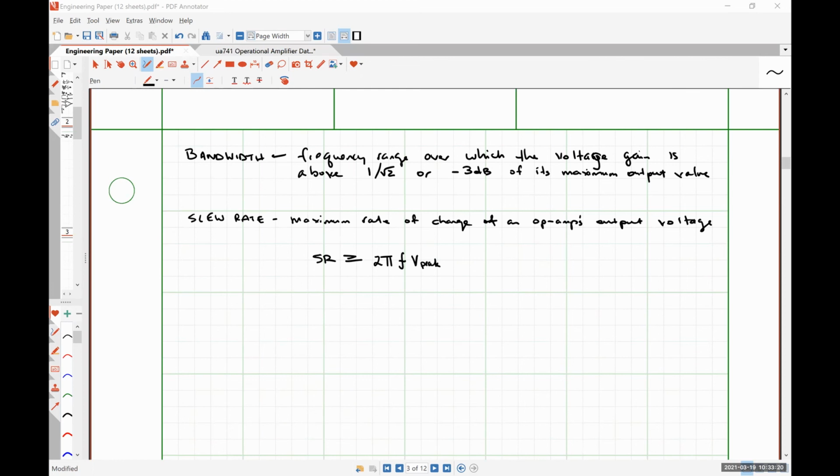And you can get that just from looking at it as from an impedance relationship, where it's a non-inverting amplifier where you have the voltage gain is 1 plus Z1 over Z2 for this guy. So that's not real difficult. How does the addition of the input bias current affect the linearity of the circuit? That's a good question. You guys figure that out. I'm not going to answer literally all 7 of them for you.